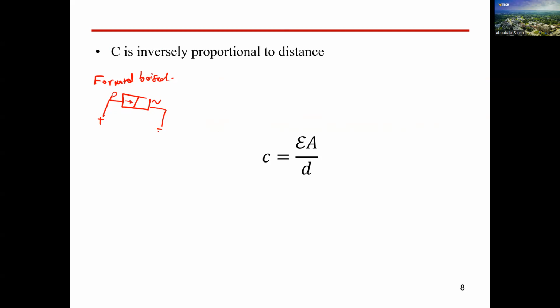And the same is also for the negative charge. The negative charge with the negative of the supply will move the electrons to that side, which means it is going to make the depletion region decrease. So the depletion region will decrease here. This means distance decreases. This is in case of forward bias. And decreasing distance means the capacitance increases and the resistance decreases. The resistance decrease means current will flow. So this is the concept now of the forward bias.